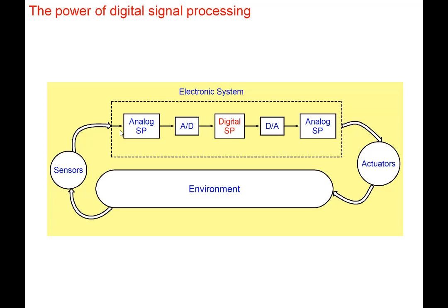If you want to divide two analog signals, if you want to take a log of a signal, or if you want to solve a differential equation, pretty soon you find things become difficult, right? And that's where the other power of electronics comes in, which is that you convert the signal into the digital domain. So you take your analog signal that comes in, you do some analog signal processing, take an A to D converter, and you convert it into a digital signal.